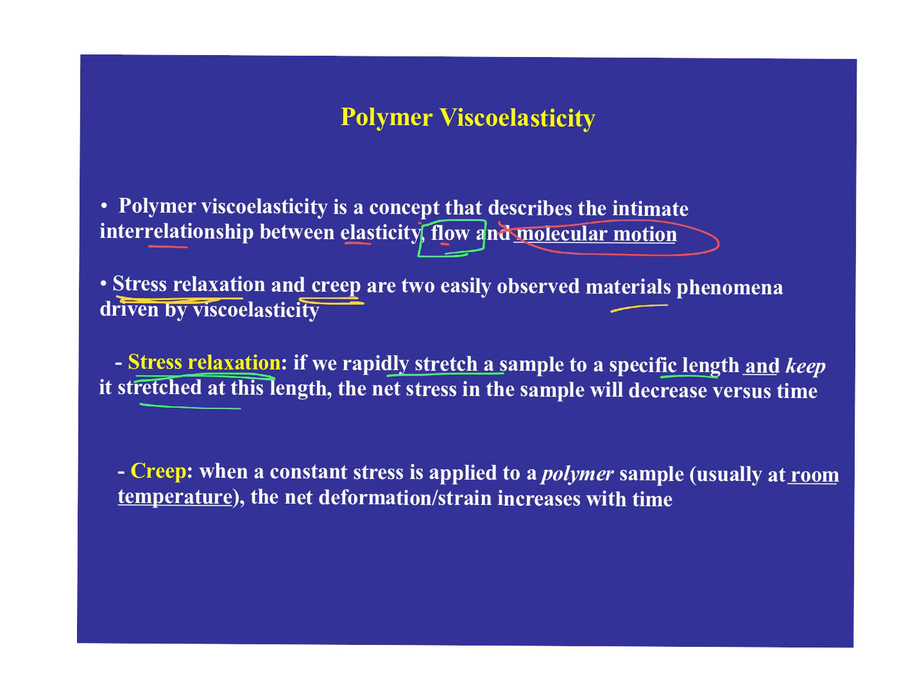Given the time sitting there at that higher level of strain, it responds via this process of stress relaxation. So we put the polymer chains under stress, and then they're at this new value of dimensions, and given time, they'll try to rearrange themselves. That can change the net stress in the sample to make it lower, to boost up entropy and decrease energy.